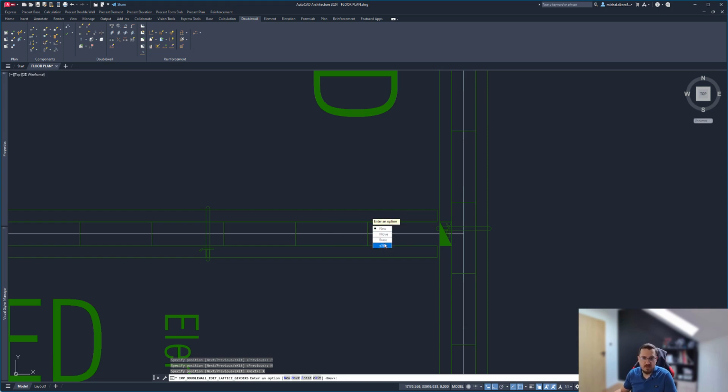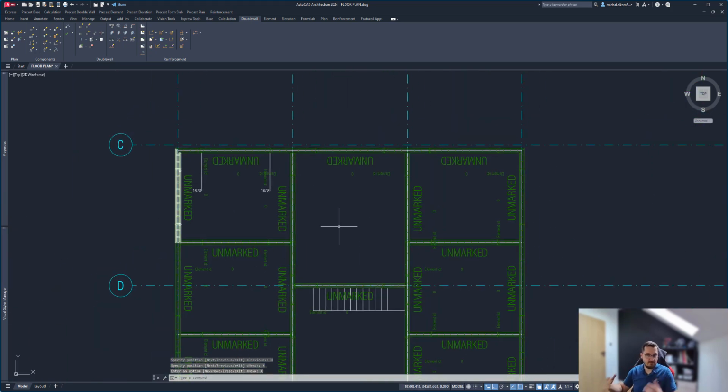But if need be, then of course you can. You can move that. If you need to delete a girder, that's how you do it, and you can create a new one, specify the location, and it will place it at that nice little spacing that you have. Let's exit and exit, and that's how you do it.